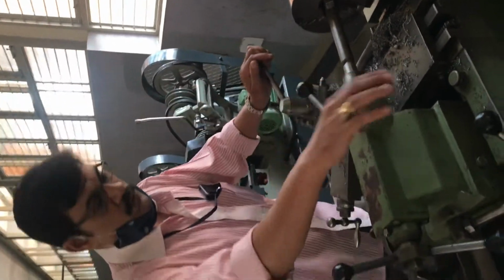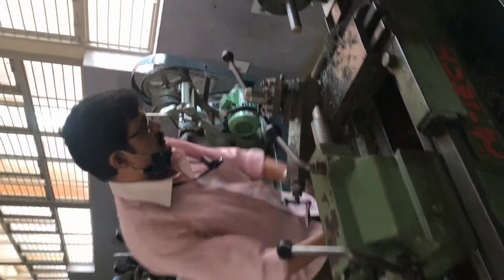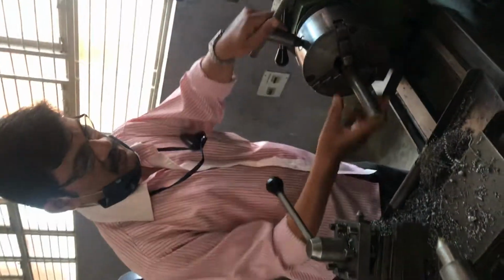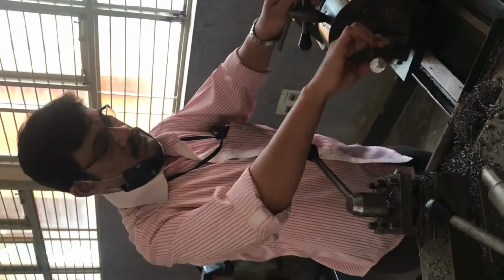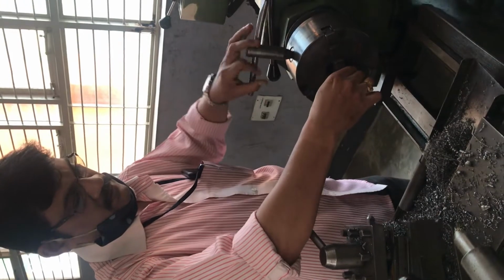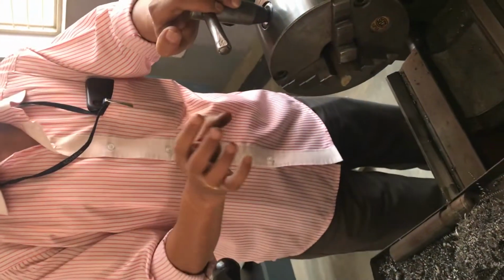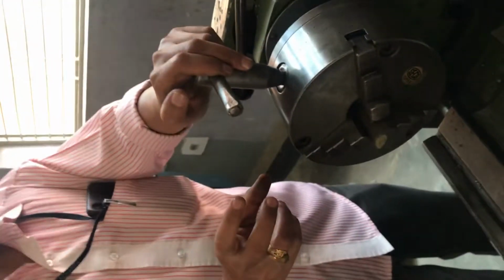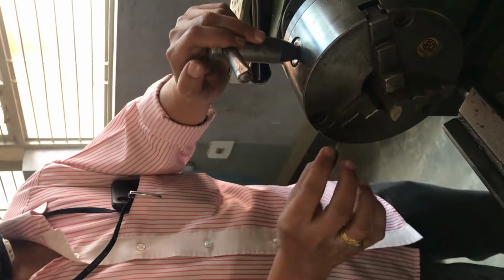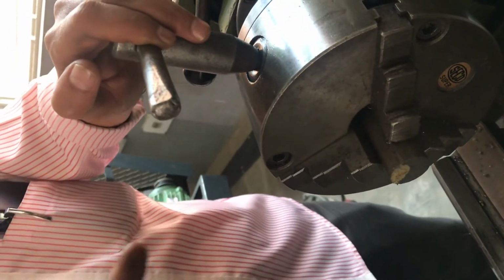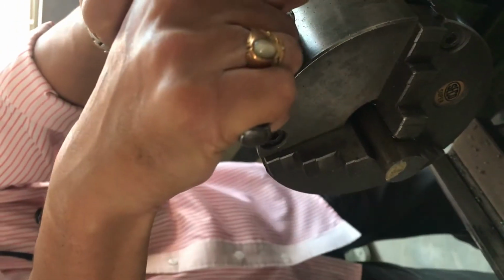So next I will show you how to do the centering and facing operation. While doing centering and facing operation, you should hold the job at short length. You should fix the job like this. Especially for centering and facing operation, you should hold only a short length. It should not be more length outside. So afterwards take the job,